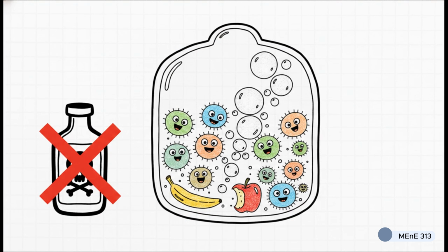We start looking at biological properties. We want a high biodegradable organic fraction, and we absolutely need an absence of inhibitory contaminants, because those will kill our microbial cultures. We are shifting our whole paradigm from high-temperature burning to microbial digestion, balancing nutrients to make sure the bacteria thrive and produce biogas.